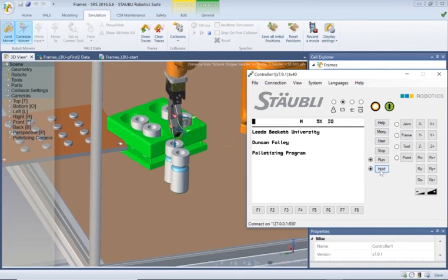Then we moved the pallet, and redefined the XY coordinates of the pallet. Because of the way frames work, the coordinate system of F pallet 2, the frame, has been updated. That's why the first position, number 2, for the pallet is 000, because it's local coordinate system against global coordinate system, and that is a really powerful